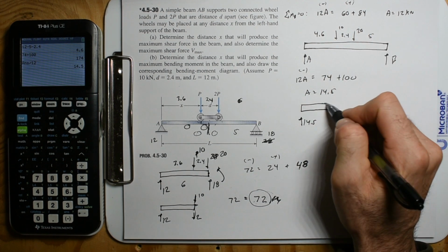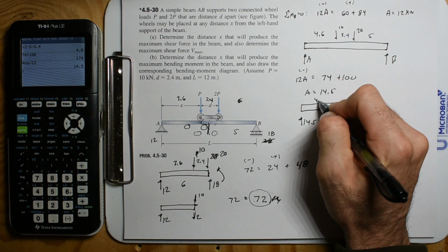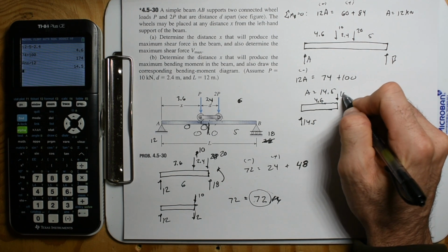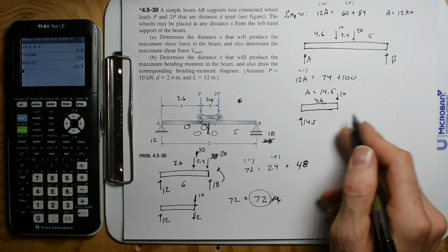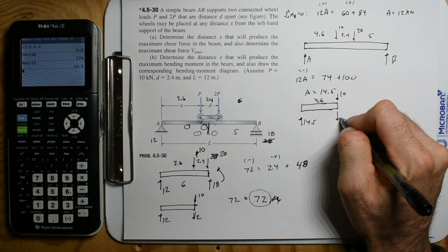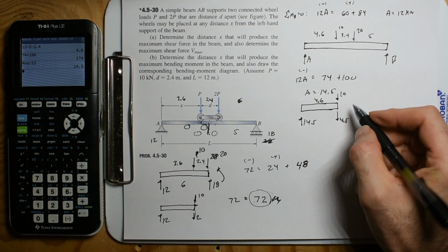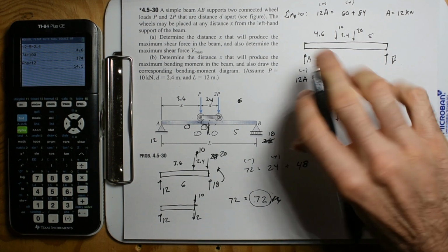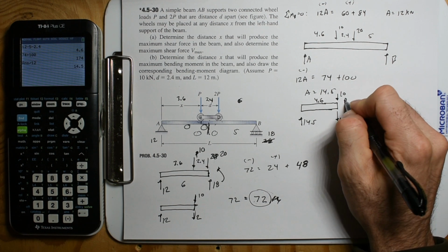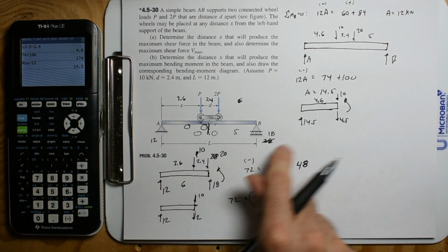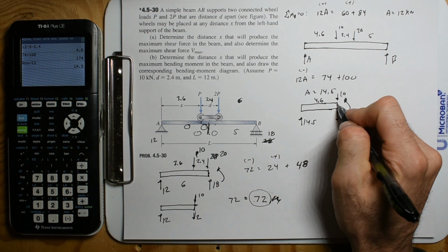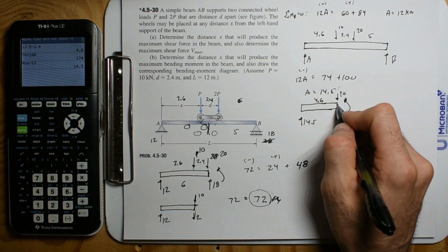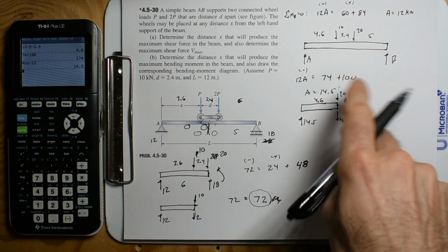We're going to go over to this 10. And so that's going to be a distance of 4.6. We're going to have 10 down. We must have to balance this, so we're going to have another 4.5 down. We're going to have a moment. So this one's going to cause a negative moment, so we must have a positive moment. And these don't generate. If we sum the moments about this point, these are in line with that point. They don't generate a leverage or a torque.